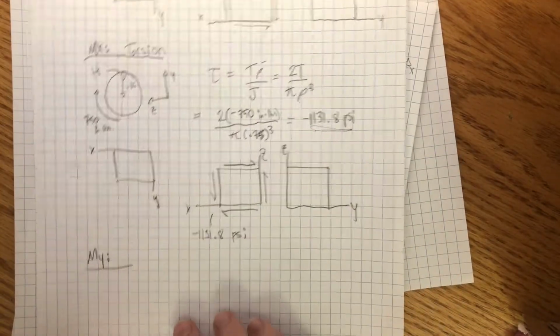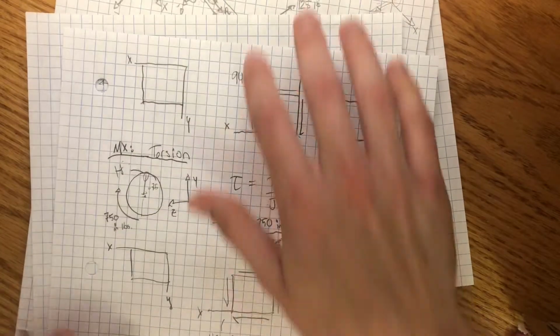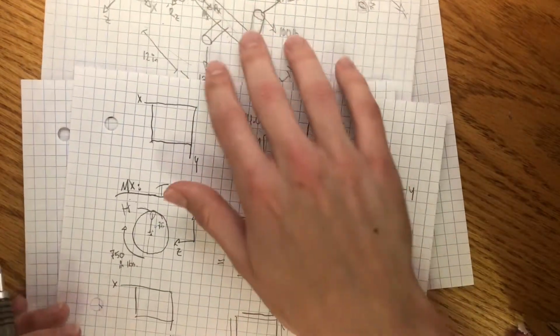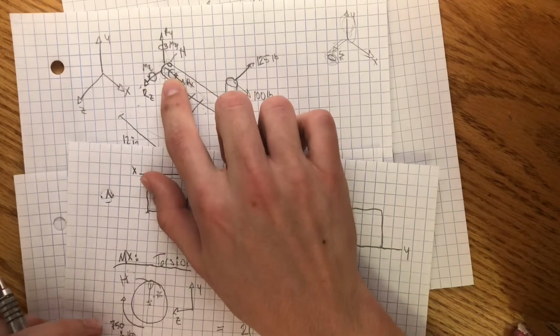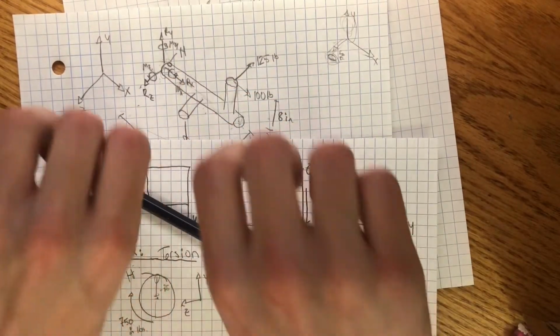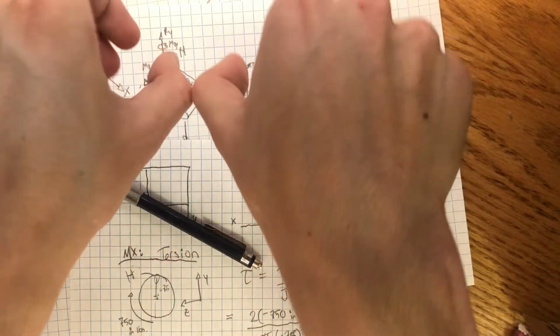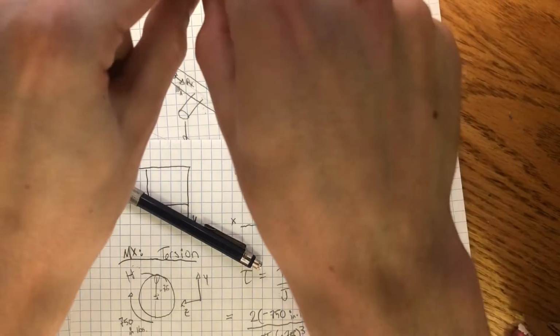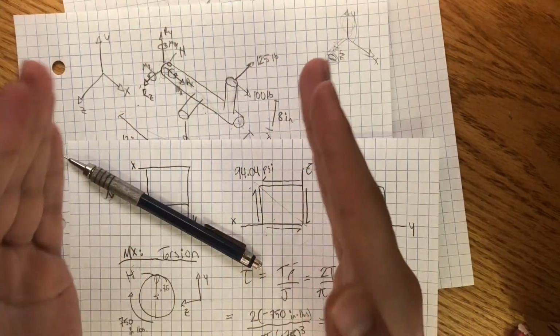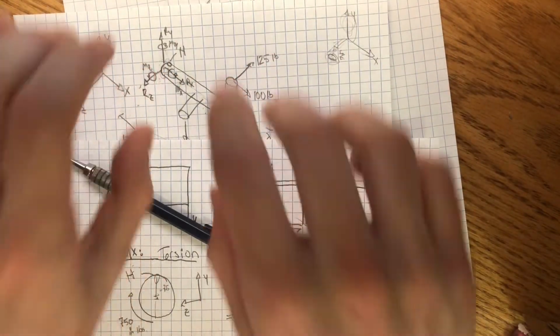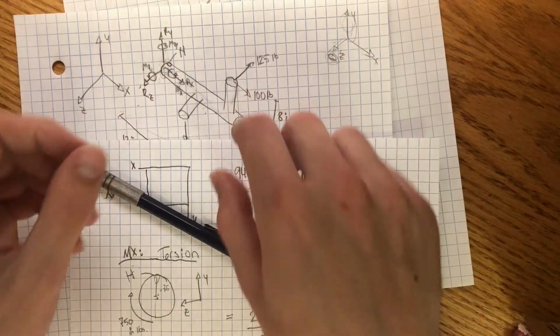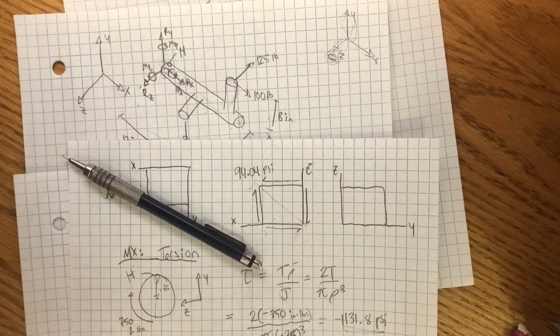And the thing about bending is that it's not going to create a shear force, it's actually going to create tension and compression. Because if you think about it, when you bend a cylinder, the top of it is actually stretching and getting longer, and the bottom of it is actually compressing. So you end up with tension and compression as a result of bending forces.